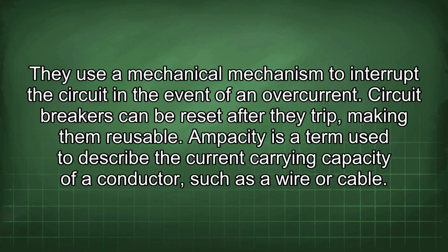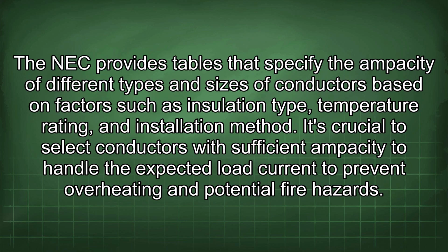Ampacity is a term used to describe the current carrying capacity of a conductor, such as a wire or cable. The NEC provides tables that specify the ampacity of different types and sizes of conductors based on factors such as insulation type, temperature rating, and installation method. It's crucial to select conductors with sufficient ampacity to handle the expected load current to prevent overheating and potential fire hazard.